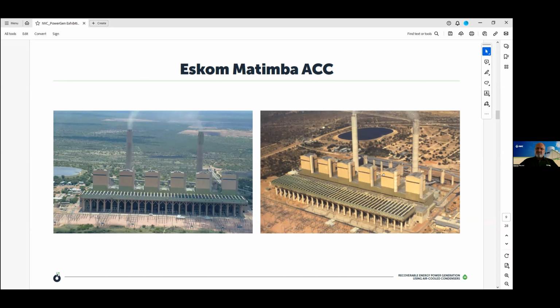If you think of an airplane, a Cessna 172, it has a wingspan of 11 meters. So in such a fan, we have 8 blades, 8 wings of such a plane almost, rotating, and they are driven by 270 kilowatt motors. That means for the whole plant, we have about 70 megawatts of power required just to drive the fans of this air cooled condenser, which is effectively almost a full new renewable energy power plant that's currently being built, like Redstone, for instance.